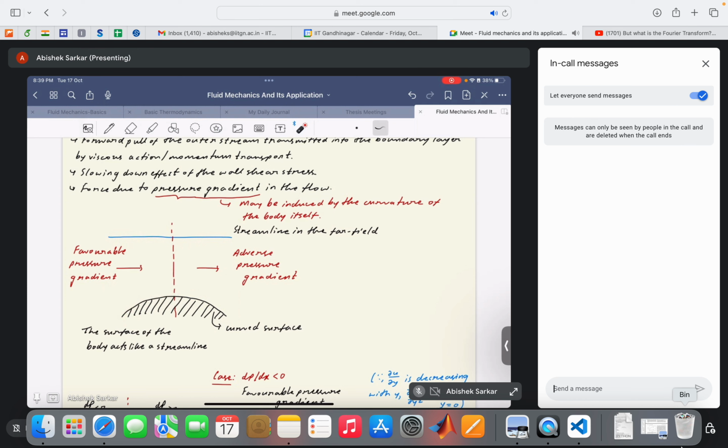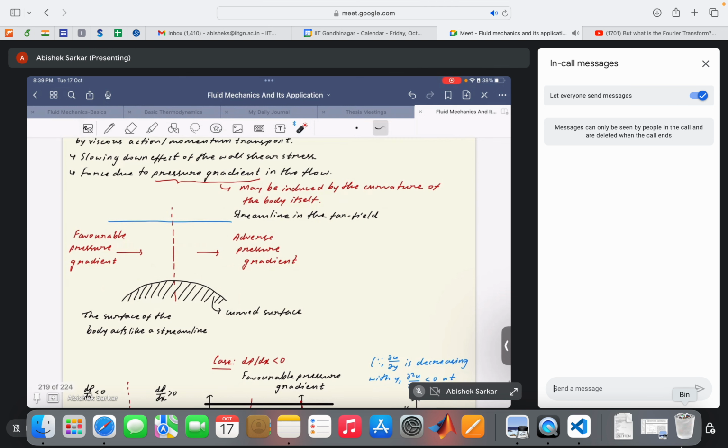Consequently, as the area increases, the velocity decreases and the pressure increases, in the case of subsonic flows. Obviously we are discussing the subsonic region. So since the area is decreasing as the flow approaches the center line, the velocity will go up and the pressure will go down.